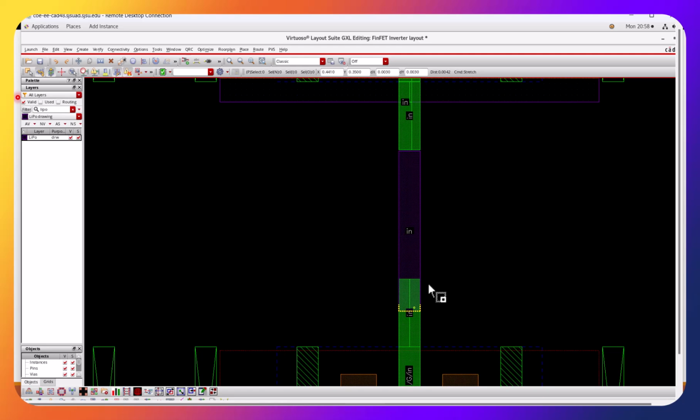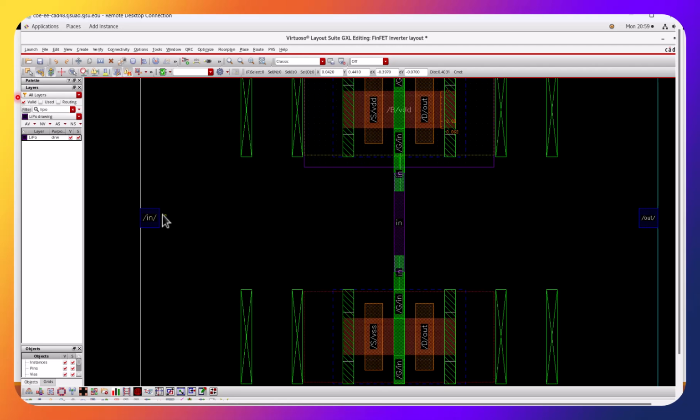Yeah, so as they said, you press S and then partial select. Sometimes it works, sometimes it doesn't. So same for this one, right? You go up and then you click on it and then you extend more so that there is overlap. I forgot about the DRC. I also believe this one needs to go out, but let's do that later. Now you want to connect the metal one to here, right? You can just create a via.